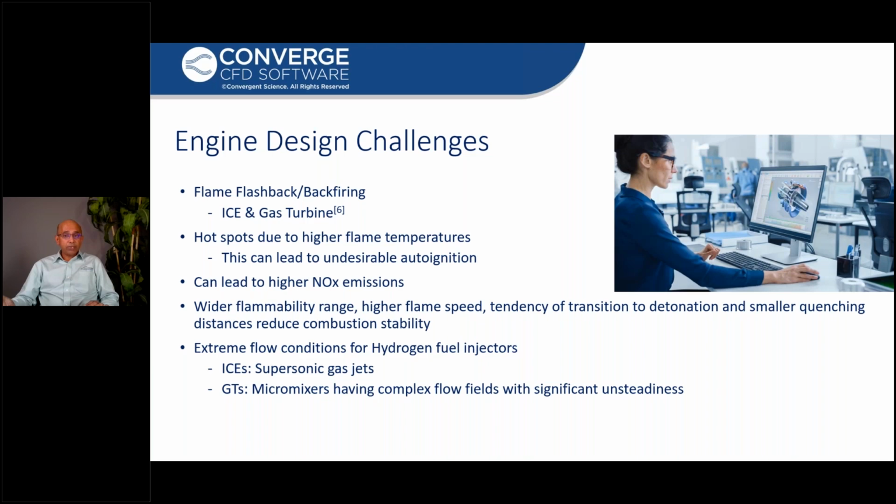Hydrogen burns hotter compared to other hydrocarbon fuels, and this can give rise to hotspots on the combustion chamber walls. This can eventually lead to undesirable autoignition of hydrogen. Design engineers should also find solutions to the impact of potentially higher NOx production when hydrogen burns in air, because it has a higher temperature, and hence the NOx will be higher.